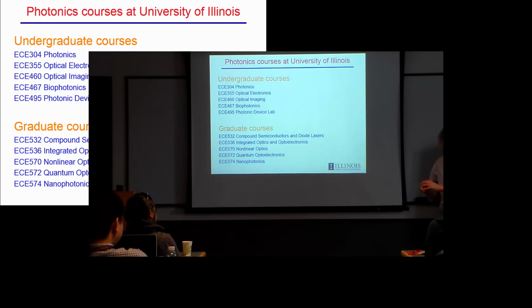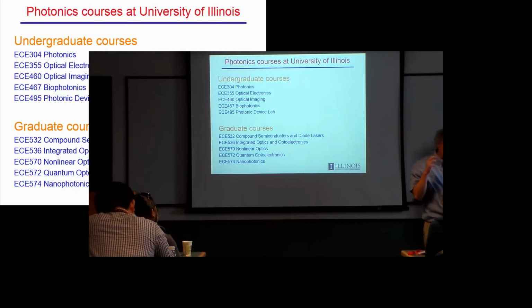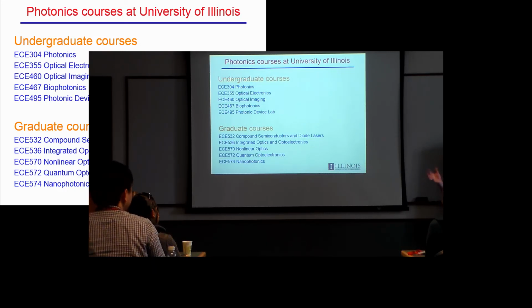But in matter, I can talk about the modes of light, which is basically saying, if I look at the light, what would be the shape? If I took a light that was inside that and shone it on a screen, what would be the shape of that light? To control that, I have to control the size of the waveguide. If I have a big waveguide, I have lots and lots of modes. For example, a typical communications multi-mode fiber has literally hundreds of modes that can be transmitted down the fiber. Well, that turned out to be a problem in some cases.